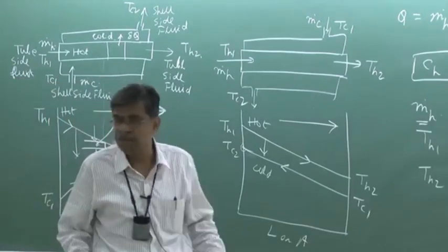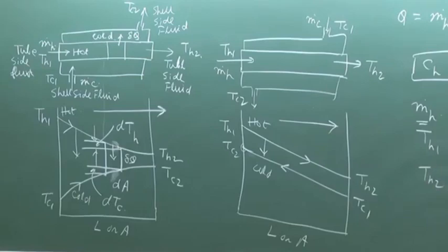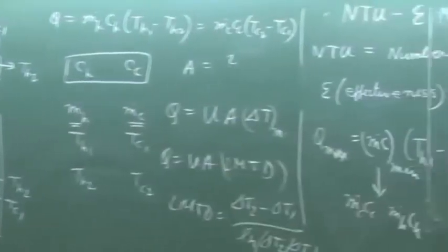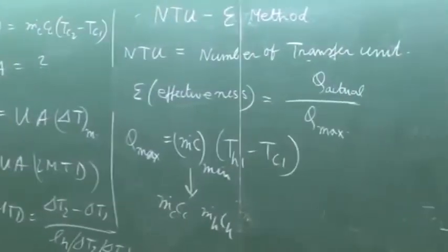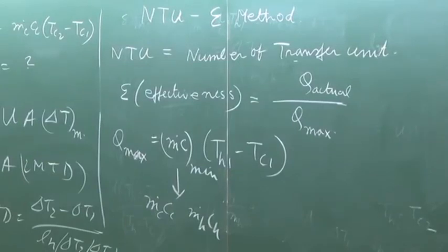Delta S universe can be 0 in an ideal situation of a reversible process, a quasi-static process, but can never become less than 0. It is impossible. So therefore, in a parallel flow heat exchanger, it is not feasible at all by the physics.